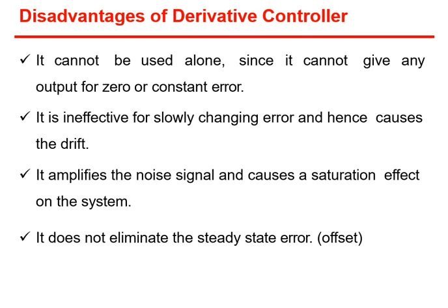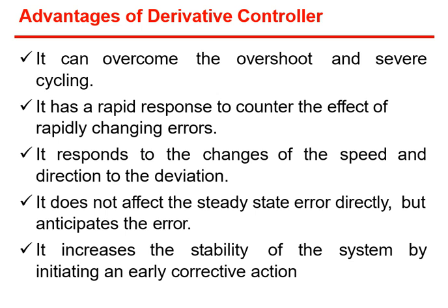Now again, there are some disadvantages of the derivative controller. It cannot be used alone, since it cannot give any output for zero or constant error. For zero or constant error it is not affecting, which we have seen in this point.